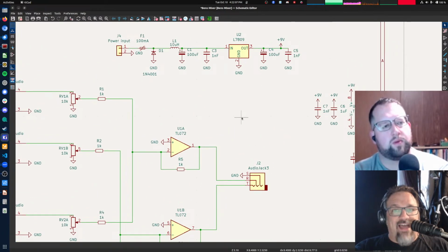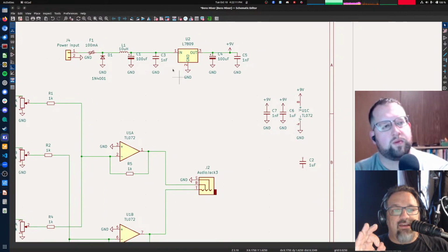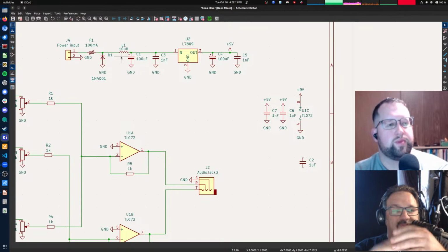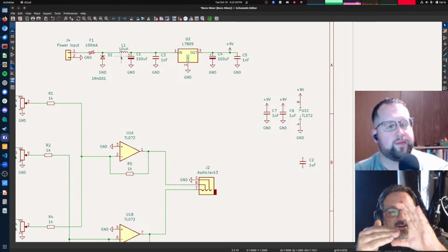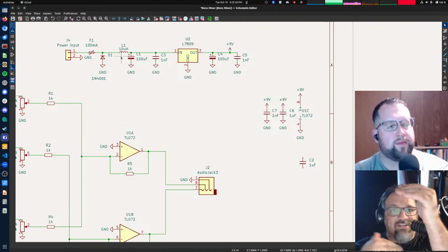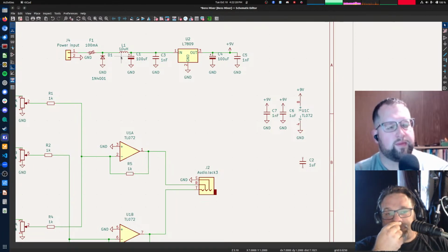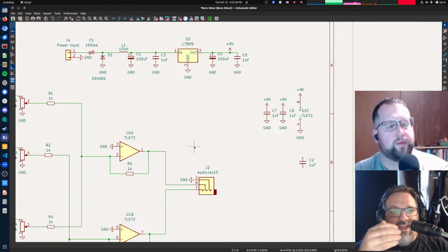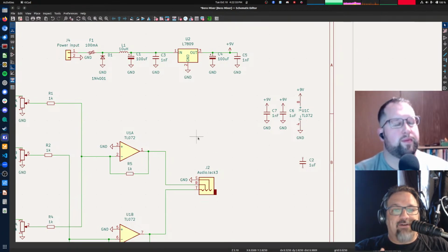So that's one way to do it, is to use an AC input, and then you end up using an isolation transformer, and you ground the center, with the diode bridge and various other things. You end up with a positive and a negative voltage regulator, and it gives you positive and negative voltages above and below ground.